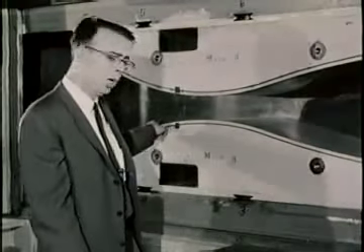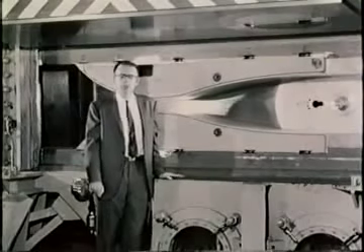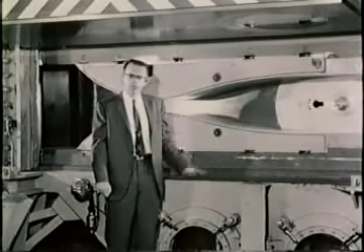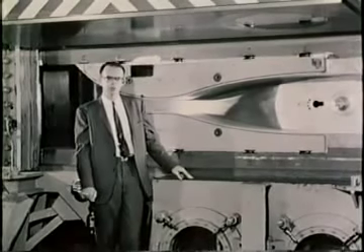The heart of the problem is the behavior of a compressible gas flowing at high speed through a converging, diverging nozzle. We'll begin with the phenomenon of choking, or sonic flow at a throat. We'll encounter shock waves and expansion waves when we come to the supersonic part of the flow. And finally, we'll look at the problem of bringing a supersonic stream efficiently to rest.